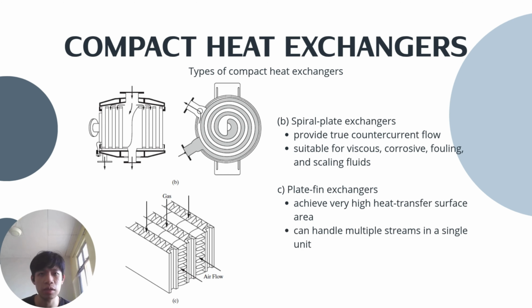The second is the spiral plate exchangers. It provides true counter-current flow and is suitable for viscous, corrosive, fouling, and scaling fluids. And the third one is the plate fin exchangers. It achieves very high heat transfer surface area and it can handle multiple streams in a single unit.